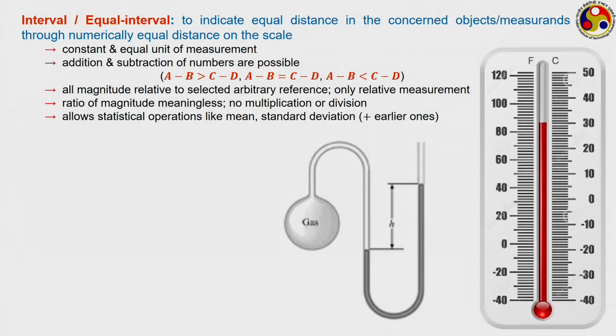Here I have another example, a common manometer. You have probably heard or learned about this in your fluid mechanics course. Here this arm is open to the atmosphere and this arm is connected to the container whose pressure needs to be measured. The fluid columns in both the arms show a height difference of h, and so the difference in pressure between the two is equal to h rho g, where rho is the density of the manometric fluid and g is the acceleration due to gravity.